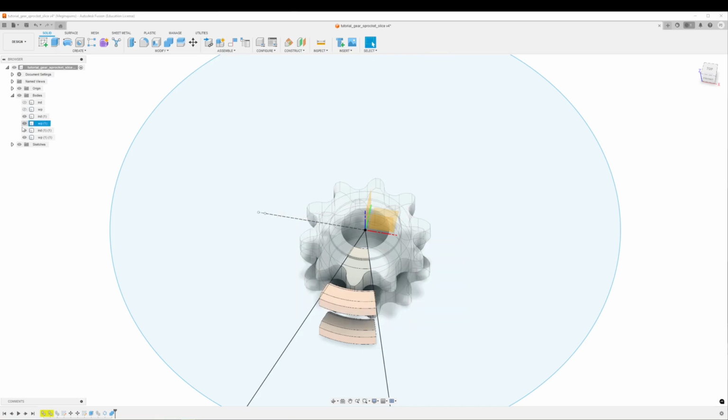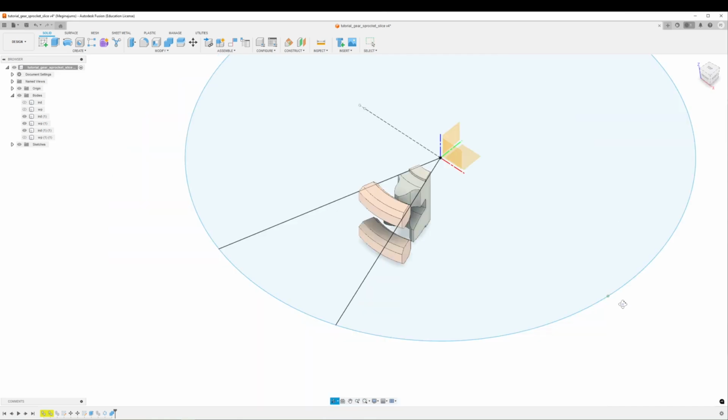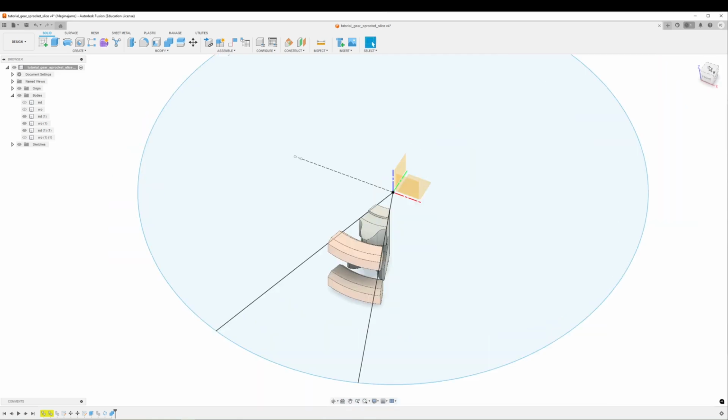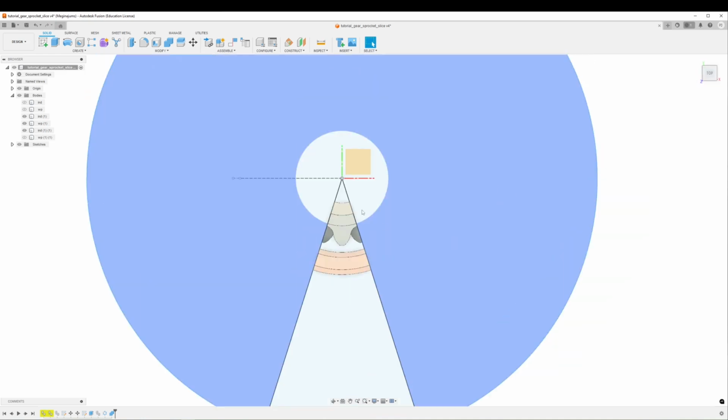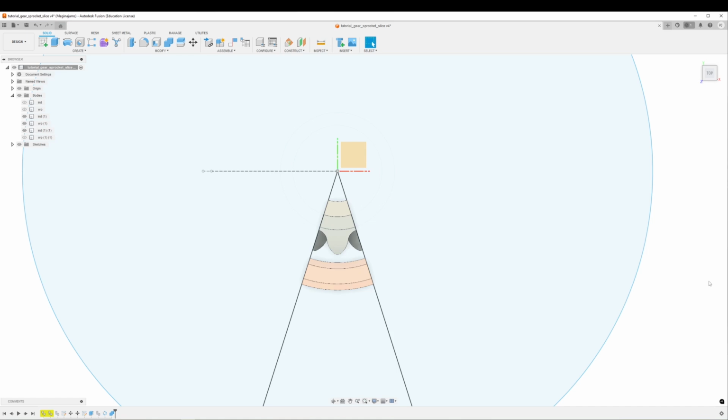We also suggest centering the geometry around one of the axes, X, Y, or Z, since it will help with result visualization later on. However, it is not mandatory. If you choose to add your own airbox as well, make sure that the previous points are true as well. It is cut on the same plane and is centered around one of the axes. If everything has been created correctly, then CENOS will have no problems generating the airbox for you.